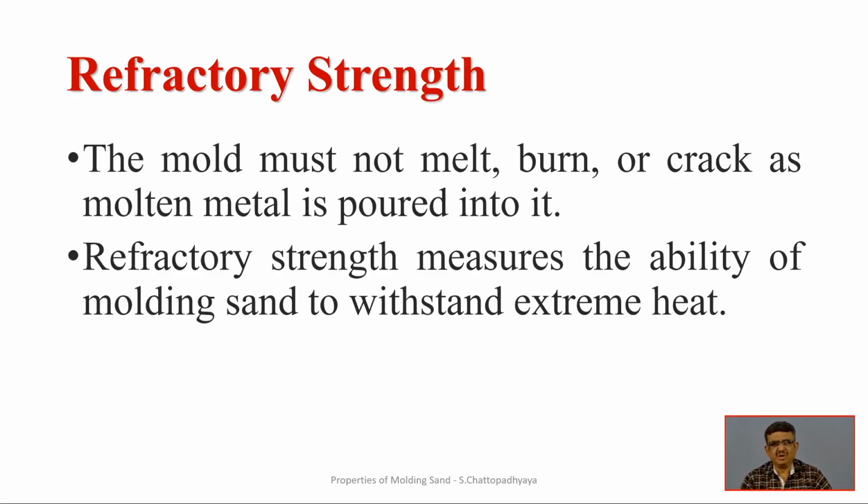The mold must not melt, burn or crack as the molten metal is poured in, and molten metal is of a very high temperature. It is a difficult temperature to negotiate with, and the refractory strength is ensured in order to have proper quality castings coming out of the casting process.